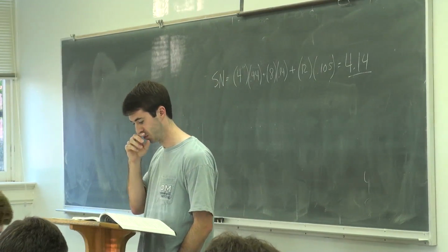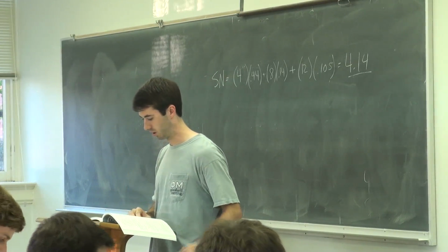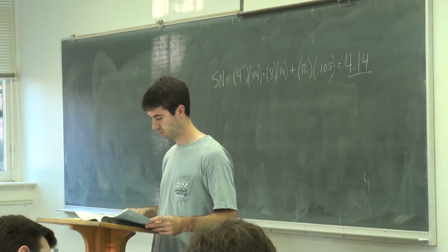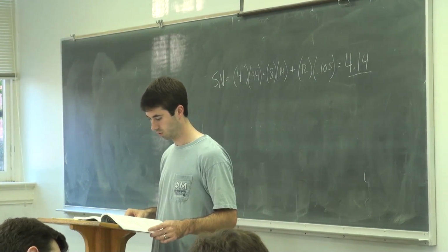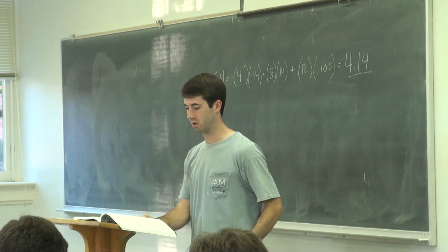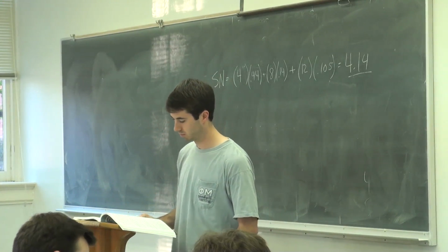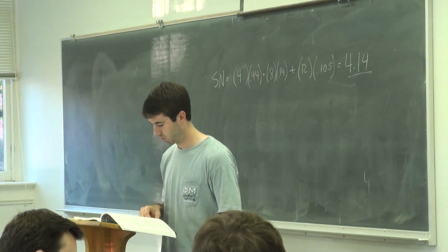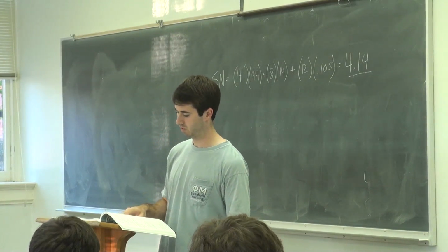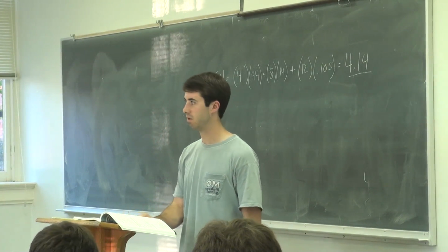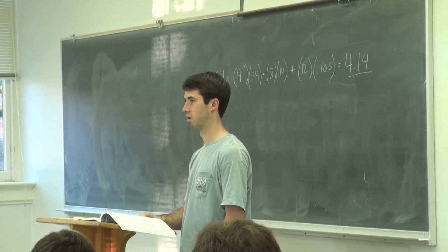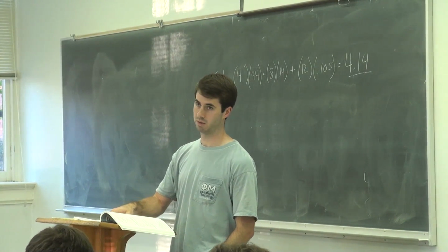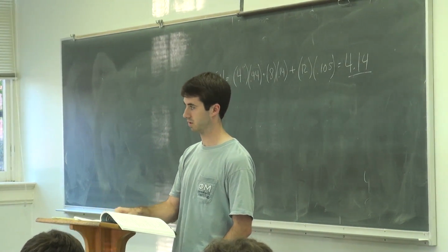Another question that could have been asked from that is something like, what would be the expected compressive strength of a concrete mix with a 0.5 water cement ratio cured in air versus cured in water for 20 days? And this chart at the top left, that's why these kinds of things are in there.